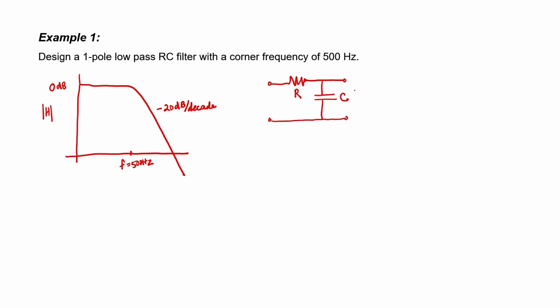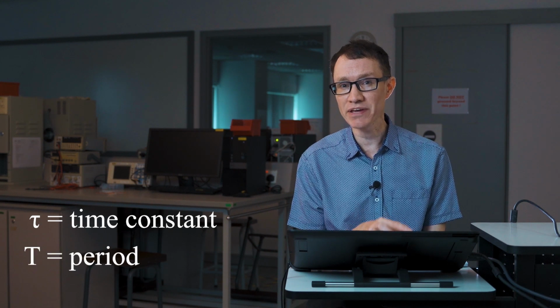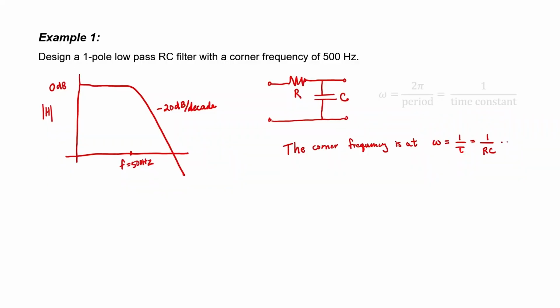We learned that for this particular filter, the corner frequency is at omega equals 1 over RC, where RC is the time constant, or tau. By the way, a common point of confusion here is that tau is the time constant. It's not the period, say, of a periodic signal or a sine wave. They both have units of seconds. Omega equals 2 pi divided by the period, and that's a bit tricky. It's the frequency that's related to 1 over the period, but here the omega is related to 1 divided by the time constant. So the point here is don't get time constant confused with period. They're two completely different things.